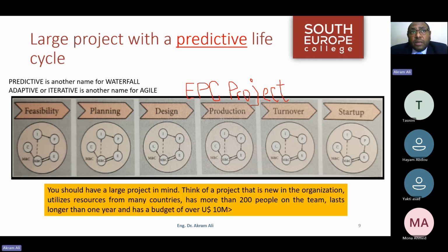For example, if you have special steel pipes, steel pipes of a special grade, like X85, they will need to be ordered and made to meet such a higher specification, so it will take a longer time. Also valves, for example, in the oil and gas sector, take a very long time to produce.